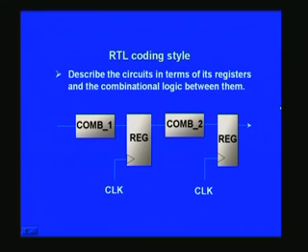It is normally referred to as a pipeline, which we will cover in depth later on when we deal with arithmetic circuits as such. And for the time being, this is enough if you know that RTL coding style is basically based on separating out combinational as well as sequential circuits as such.